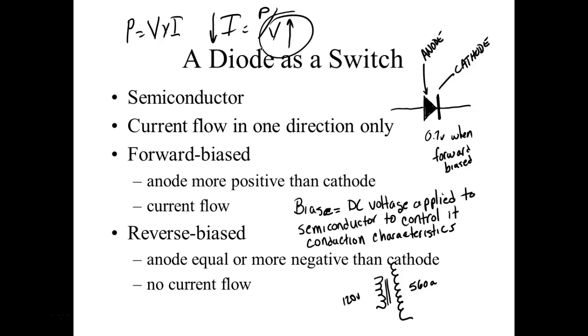I'm going to have to start stepping that voltage down. Because two things: I'm getting closer to earth ground, and another thing, I'm getting closer to me. Right? You understand? So what we can do is step that AC voltage up for transmission, and step it down for safety. So even though there might be 2,300 volts up there on your power pole, when it gets to your house, you're getting 240 and 120, right?